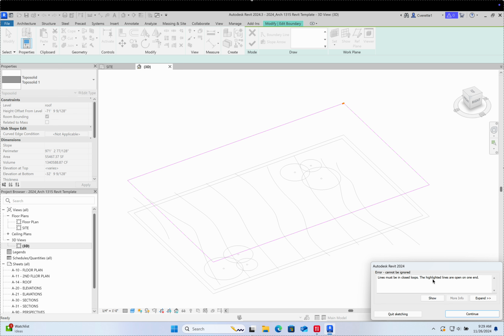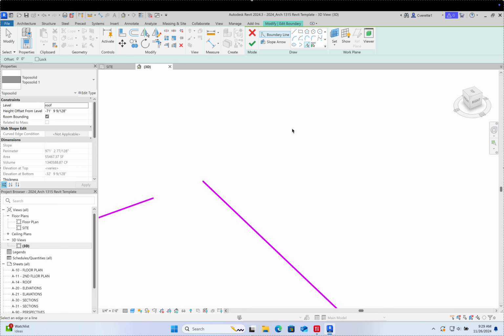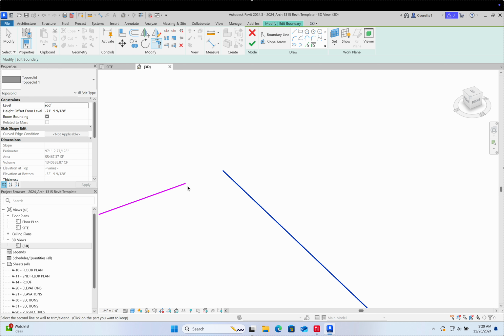That makes sense because you guys learned in Rhinoceros the difference between an open and a closed shape can make all the difference, right? And Revit won't even let you make an open shape. That's how constricting this program can be. So in my case, I do need to connect those first. Now trim is at least the easier one. I can type in TR and it puts it together.